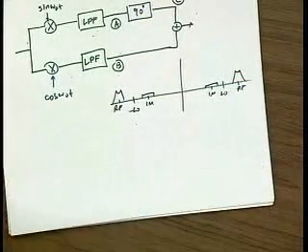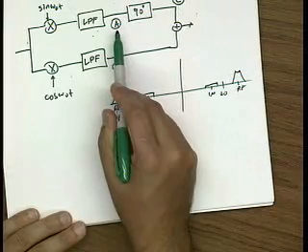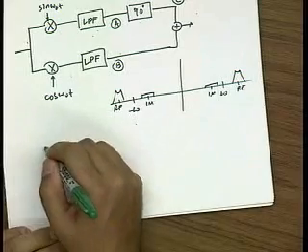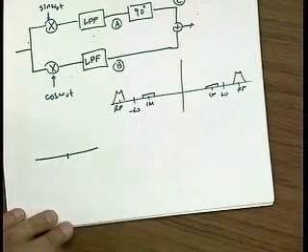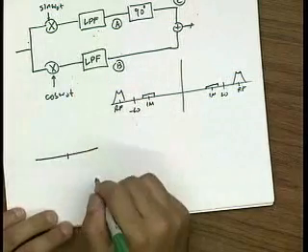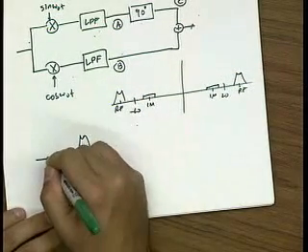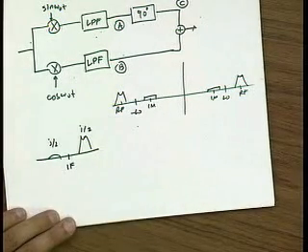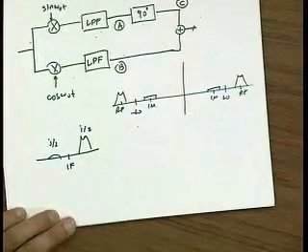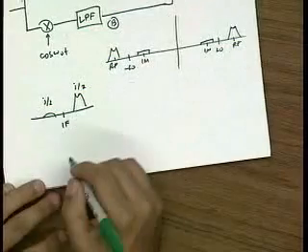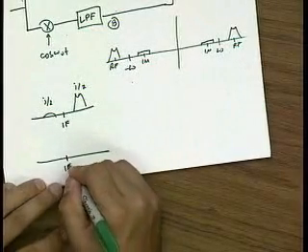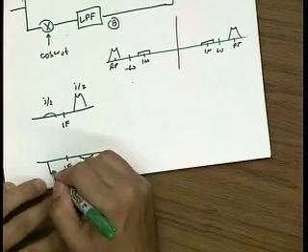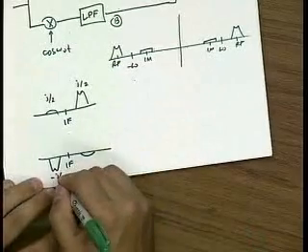Let me plot what happens to our signal at point A. Point A corresponds to multiplying by sine. I can do that in two parts. If I multiply by the first term, which is the positive frequency, I get the following. This is my IF. And there's a factor of j over 2 because sine has an extra j in it. The second term is e to the minus, and it also has a minus sign because it's a sine.